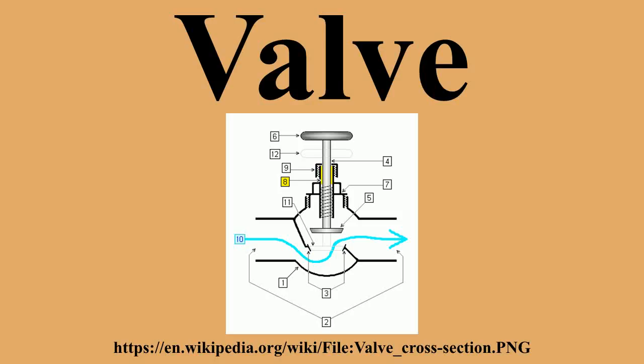Other considerations. Valves are typically rated for maximum temperature and pressure by the manufacturer. The wetted materials in a valve are usually identified also. Some valves rated at very high pressures are available. When a designer, engineer, or user decides to use a valve for an application, he or she should ensure the rated maximum temperature and pressure are never exceeded and that the wetted materials are compatible with the fluid the valve interior is exposed to. In Europe, valve design and pressure ratings are subject to statutory regulation under the Pressure Equipment Directive